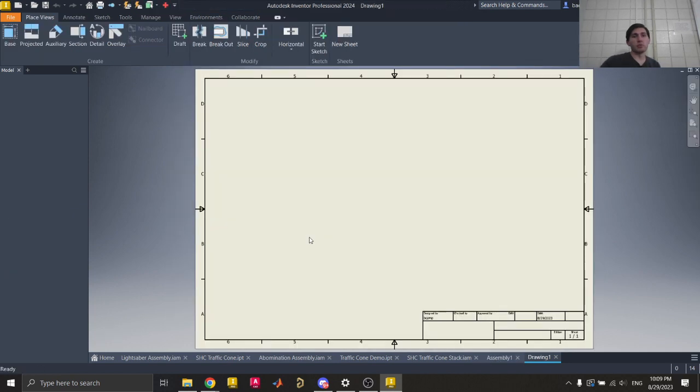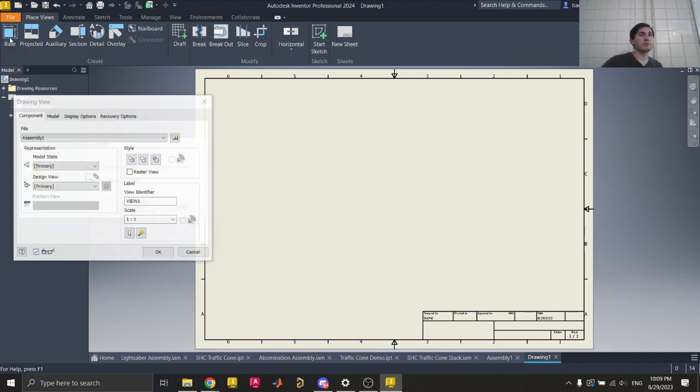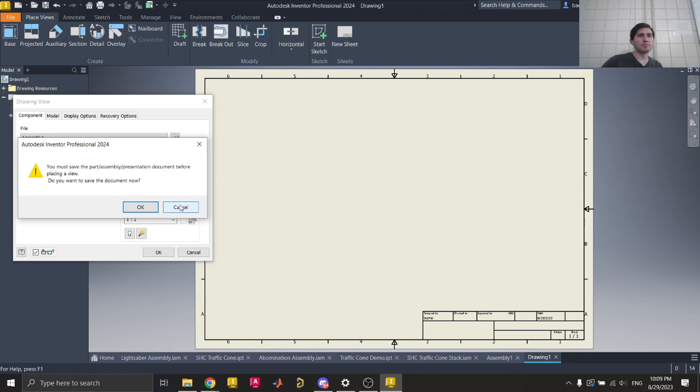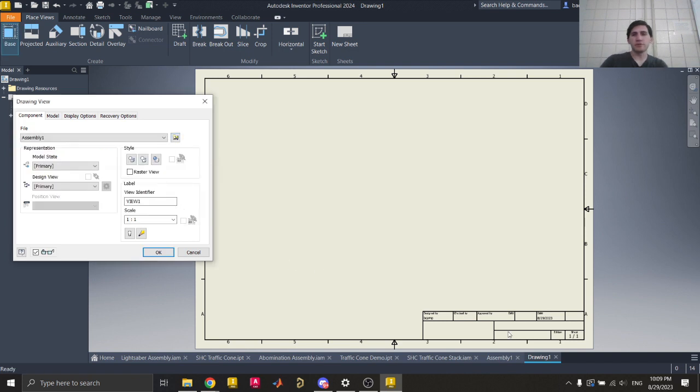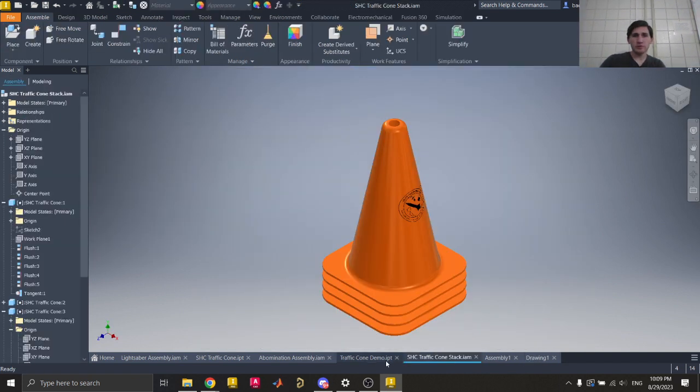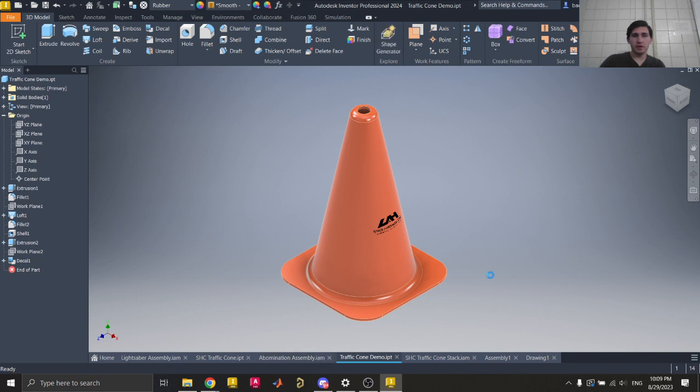You go to Make New, and then down here in any of these drawing things, I'm going to pick ISO.IDW. And then what that does is pull up a little sheet like this. If I want to have different views of a part or an assembly and add measurements to it, I can hit this little base button right here. Actually, I just realized I'm going to hit save.